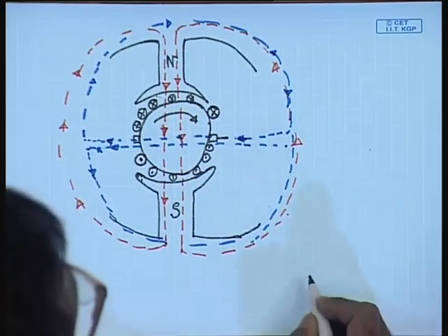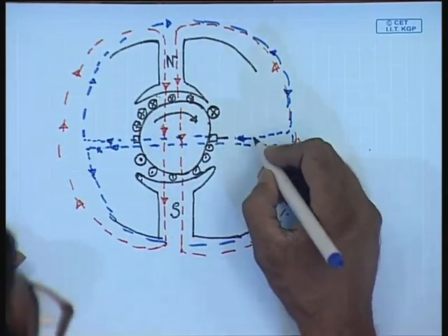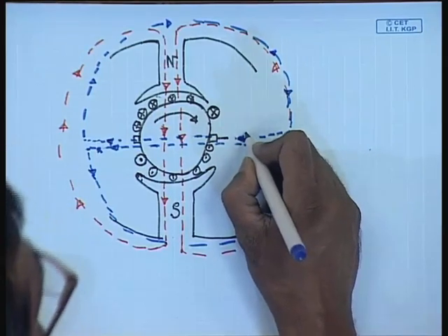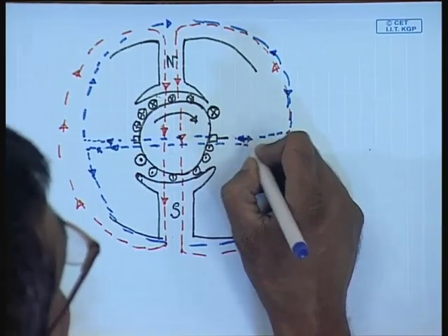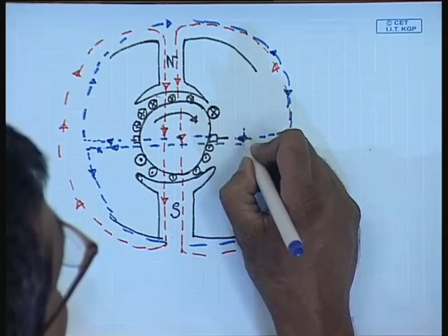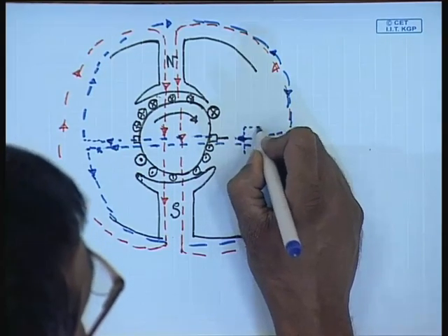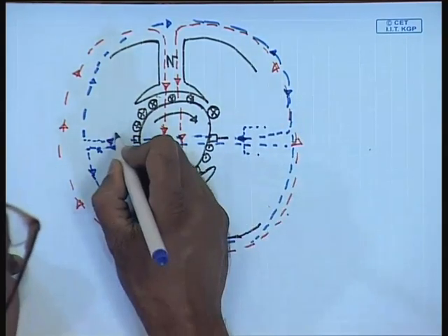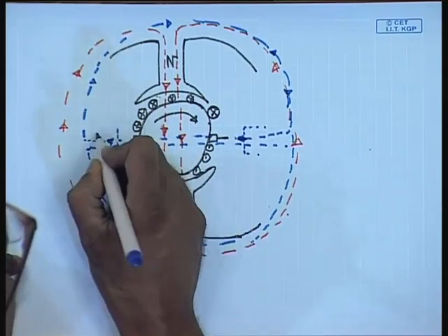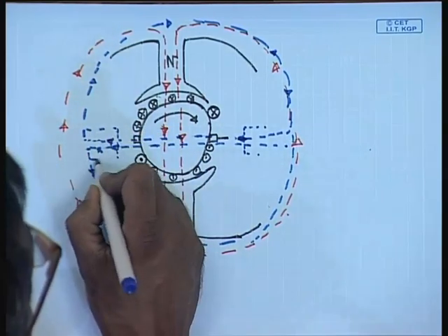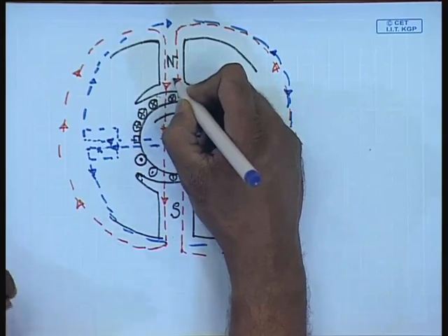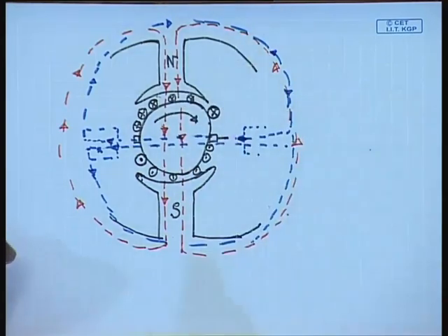In other words, the armature MMF will produce a virtual north pole at the interpolar region, a flux that is equivalent to a north pole, that is the pole left behind in the generating mode.